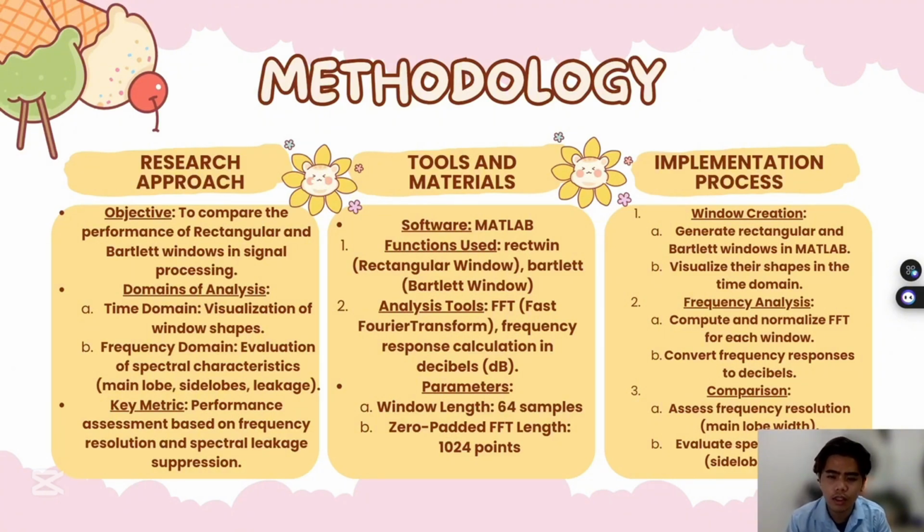The second one is the frequency analysis. We compute and normalize the FFT for each window, and we convert the frequency responses to decibels.